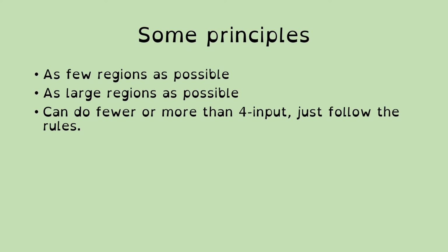And you can do fewer. So a 3 input, instead of being a 4x4 grid for your K-map, will be a 4x2 grid or a 2x4 grid. And for 2 inputs, you've just got a 2x2 grid. By the time you get down to 2 inputs, actually the process of doing a K-map is you can usually do it by inspection anyway, by being able to look at it.